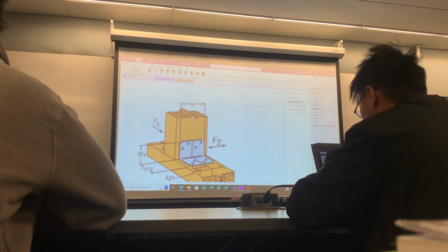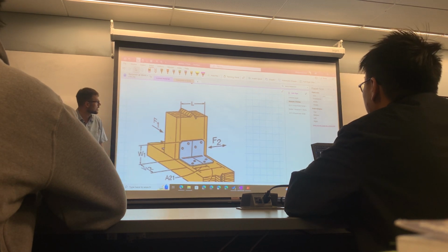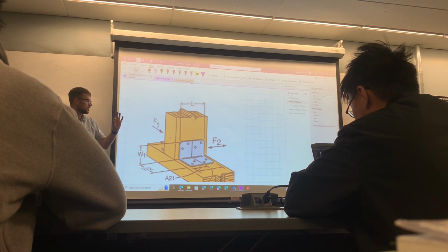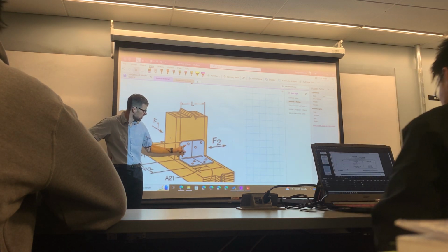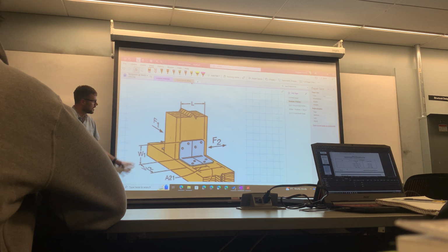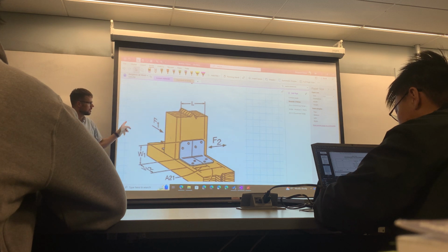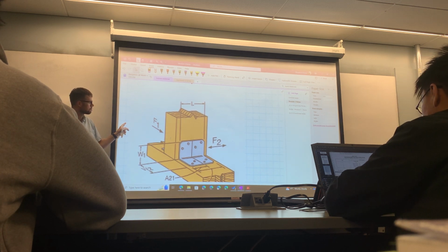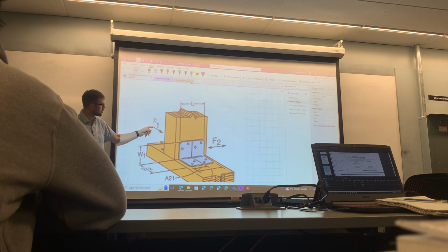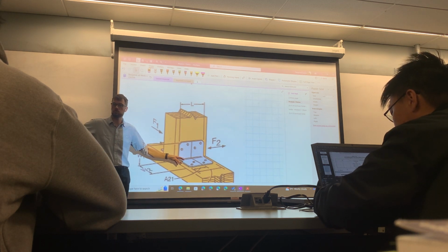And that's why I've got this photo. All right, when the nails are insufficient for the wind, we put these steel angles, I call them clips because it's gauged, it's very thin steel. But you can see they're connected with the nails into the bottom plate or the top plate, into the plate and the stud. And this reinforces direction for F2, and we can find F2 from the W prime F that we've resolved from the wind. And then this force as well. Can you see how this would reinforce the nail connection?